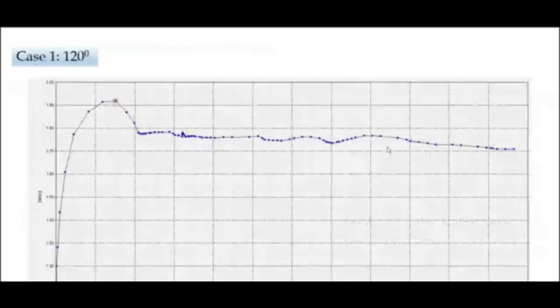So in this case, for the toppling case, for the same strength parameters, the factor of safety now reduces and is around 1.9. That is where your jointed rock mass model is a very advanced model, I would say, and it is able to capture most of the failure mechanisms in rocky strata. And I feel that this can be utilized for a number of studies where